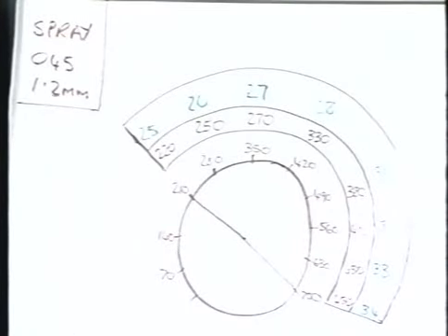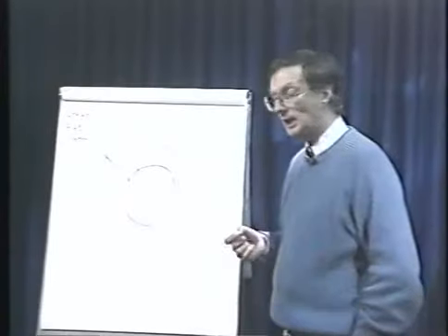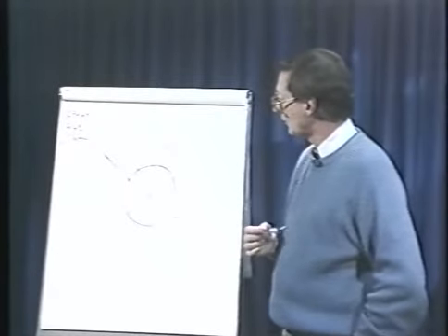In the current range of 220 to 450 amps, we can achieve almost up to about 19 pounds per hour. An ideal starting point with the 045 wire would be approximately the 2 o'clock position. You want to be somewhere between 400 and 500 inches a minute. Do you remember with the 035 wire, it was in the range of 500 to 600 inches a minute. The 045 wire in the range of 400 to 500 inches a minute, between the 1 and 2 o'clock position, is again an ideal starting point on 1/4 inch.